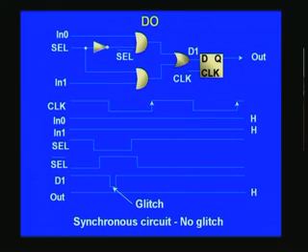Another thing we talked of earlier is the glitch, which is an unwanted, uninvited guest that you would like to eliminate. For example, this circuit gives a glitch as far as this combinational circuit is concerned, and a narrow pulse like this is known as a glitch. How it is produced, we will just have a look. These are all plain AND gates here with an inverter here, and finally these two are ORed here, and then applied to a D flip flop.